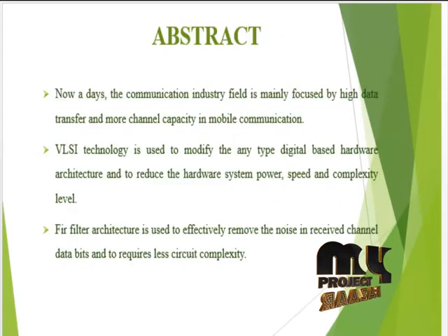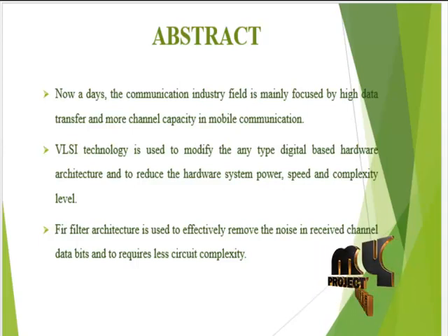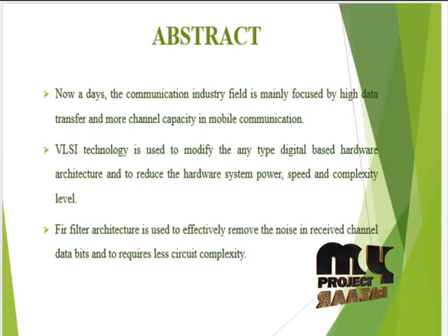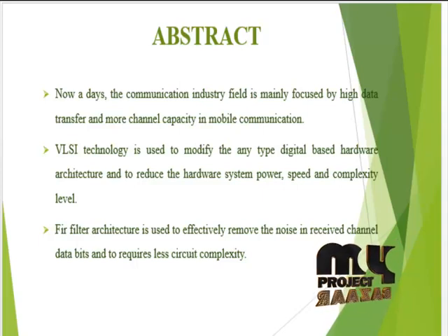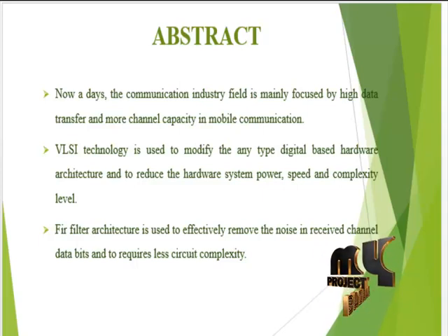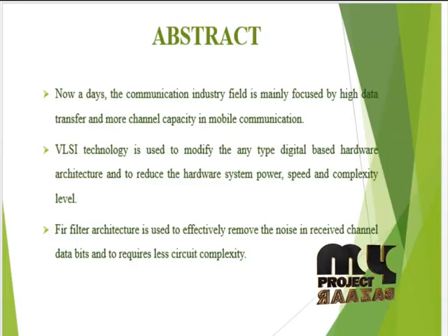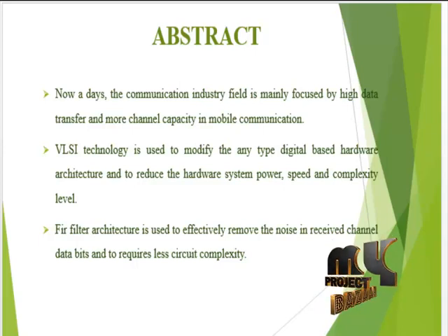Now we are going to discuss our project abstract. In our process, we have mainly focused on a precise analysis and optimization of the critical path for transposed direct form FIR filters. The delay increment introduced by the structural adders is estimated by comparing the delay of a tap and the corresponding delay of the coefficient multiplications only.